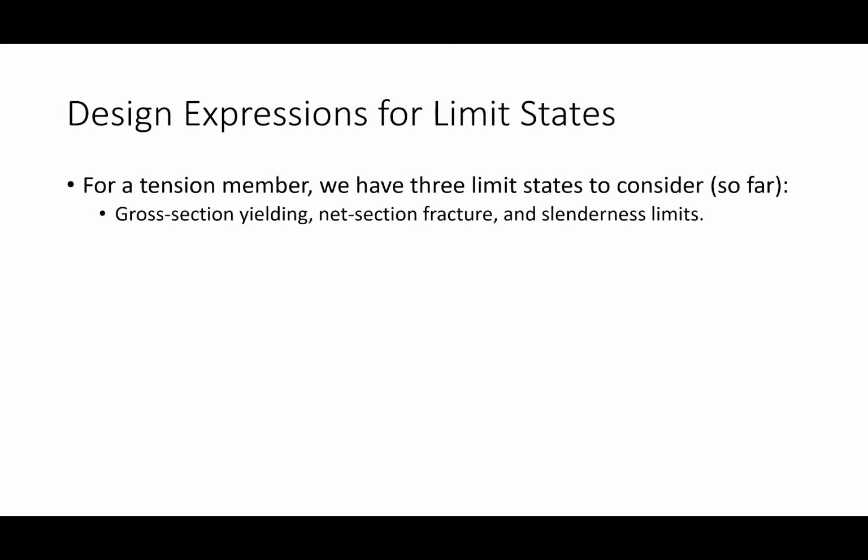Like I said, we're going to try and avoid throwing darts at the wall and just picking a shape at random. So let's see if we can hone in on a shape. And what that means is, for example, if you open up the table for angles, there are numerical properties for those angles that we would like to be able to use to select members. In other words, could I solve for a necessary radius of gyration and then pick a member that has a radius of gyration at least that, if not bigger? Yes. Okay? So that's what we want to try and do.